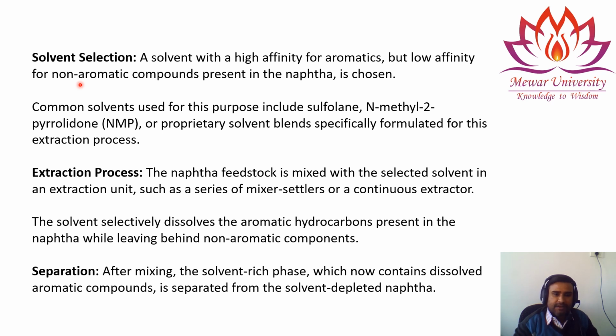In a multi-component liquid, the solvent is added and one component, the aromatic, is dissolved, and the other component, pure naphtha, is separated from it. So the naphtha feedstock is mixed with the selected solvent in an extraction unit, where the solvent that you have selected, for example sulfolane or NMP, any one, is mixed.